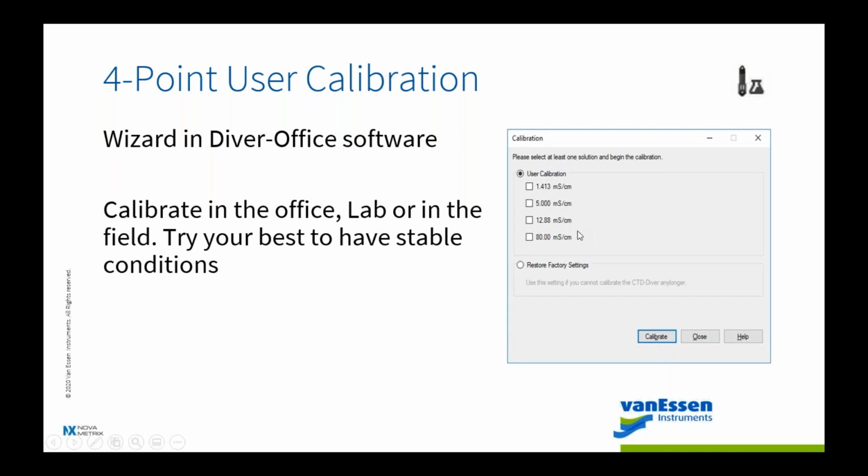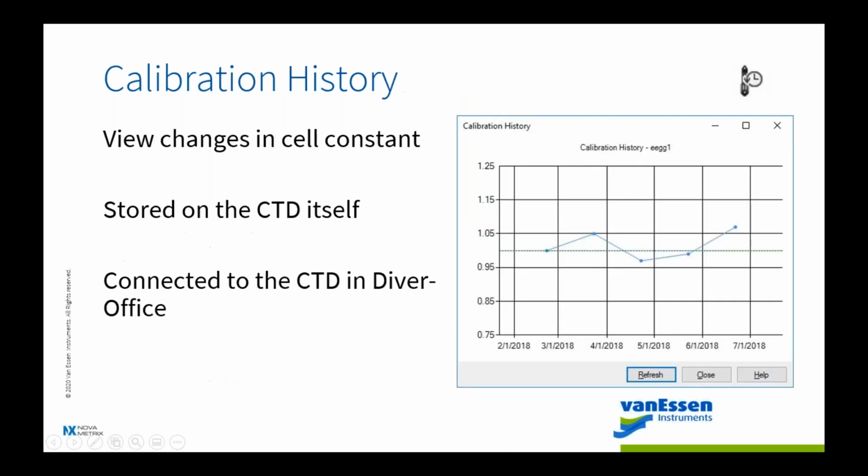Hopefully it's one of these 4, and from there it is swirling the solution, swirling the CTD, either using a reading unit holding it tight in place, or one of our cabled solutions. Swirl it in place, and within less than a minute, that unit should give you an indication that it has been calibrated by clicking that calibration button down here. This is what it looks like in the software, and you move on to the next CTD for calibration.